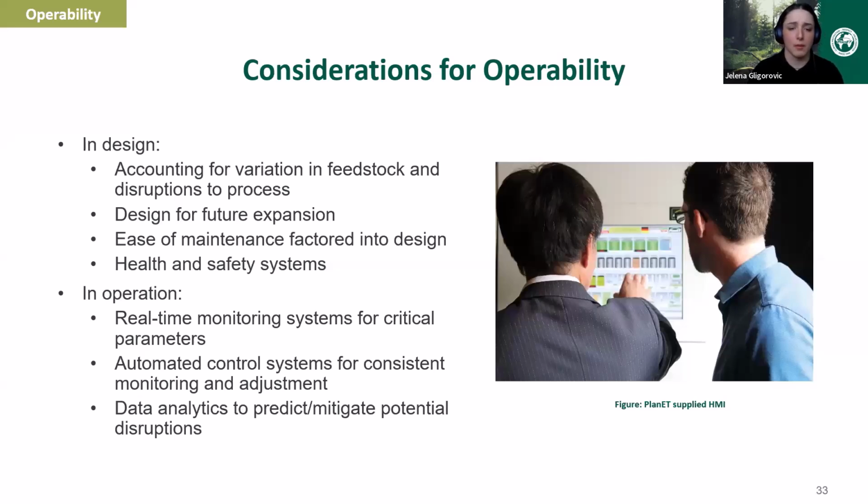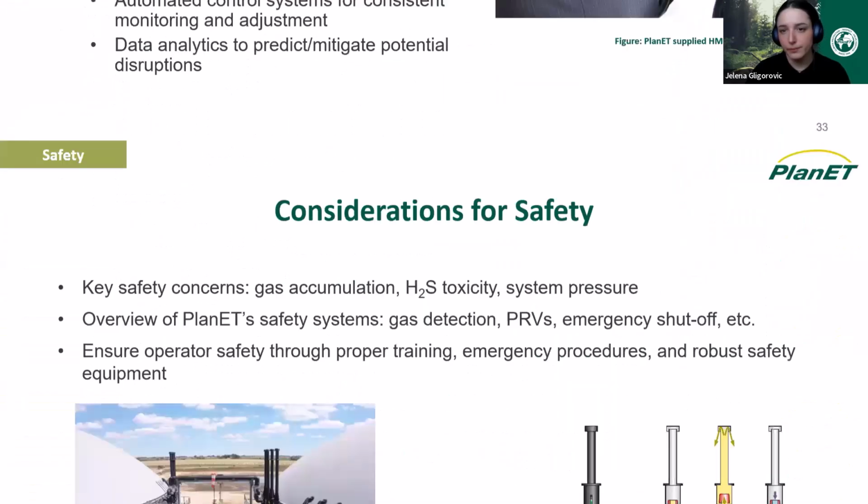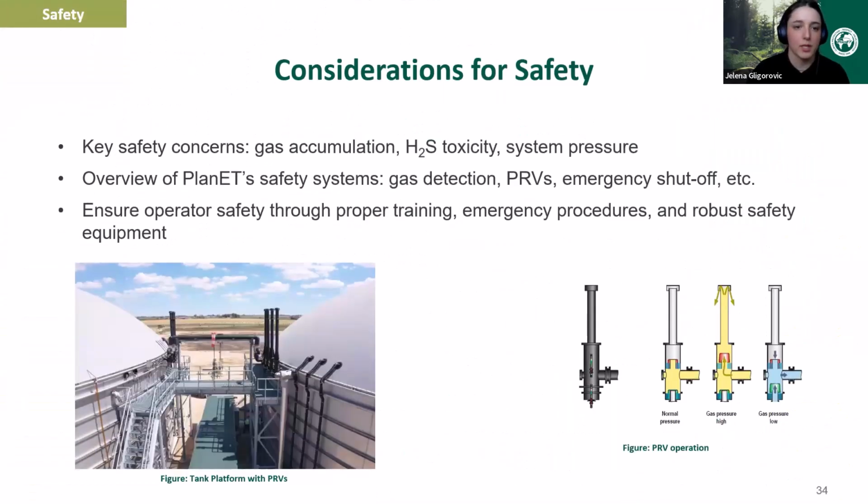So like I talked about, if you know that your feed is staying consistent, but you see a slow reduction of biogas production over time, that could be an indication that your digester requires a clean out. So things like that to consider in design. And then of course, considerations for safety, which I mentioned before.